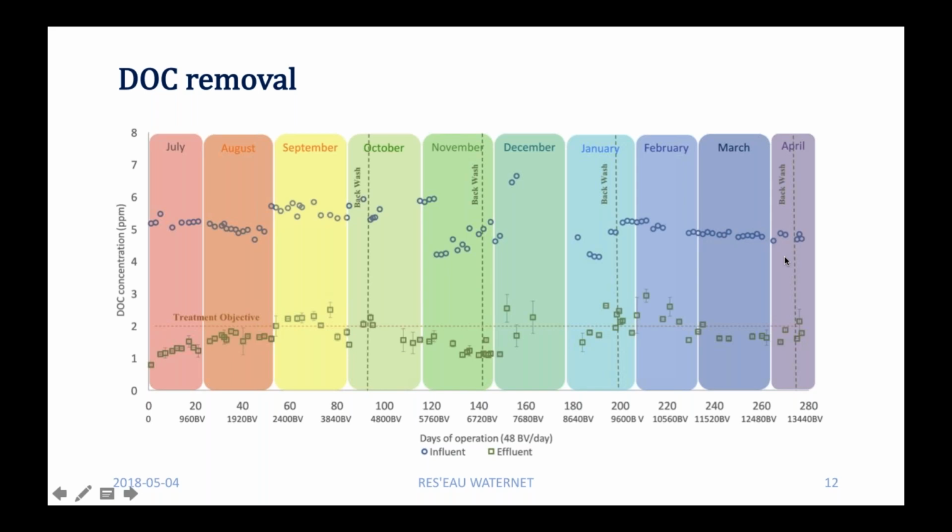What do you think caused the change in sulfate removal after 160 days? Actually, it was expected, because after a while the concentration of sulfate on the surface of the resin will be so high, because it's removing and absorbing sulfate. And during mass transfer, when the concentration of sulfate on the surface of the resin is higher than the concentration of sulfate in the source water, the resin will release sulfate. But we need to investigate more what happened at that stage.